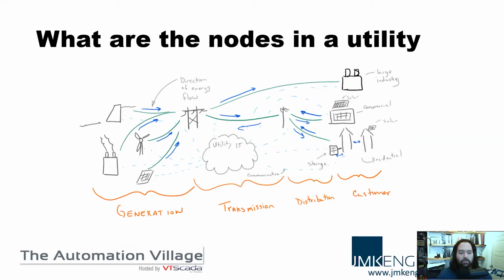Or it could be routines on a single controller. The idea is that if it's a routine, the protection engineer is the one taking care of the protection routine. For the governor control, it is the electrical and mechanical engineers working on the governor controls. At a substation, it would be something similar. The local operator will have control over everything within the fence of that substation and all components that are downstream towards the customer. This might include reclosers, capacitor banks, etc. And then all that data is brought back to the local operating control station and integrated with the local HMI.